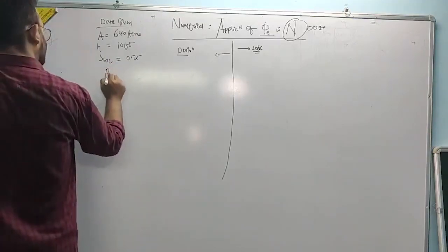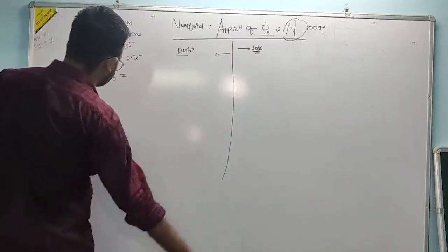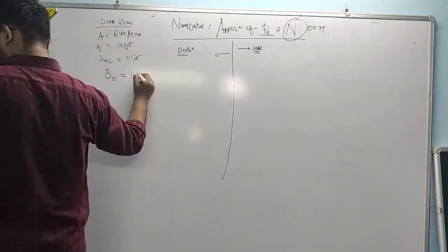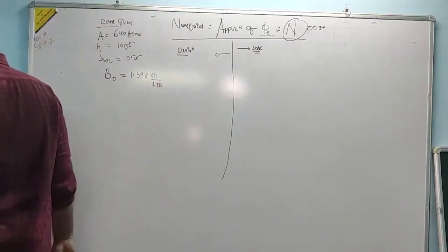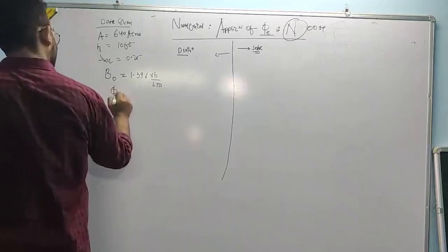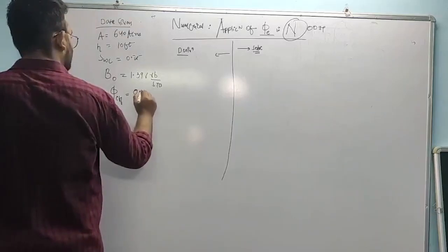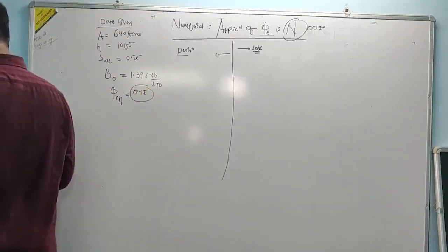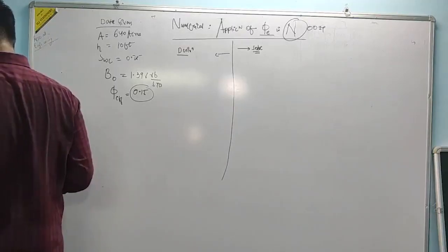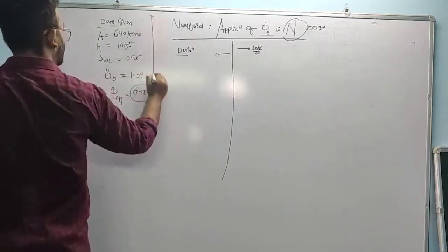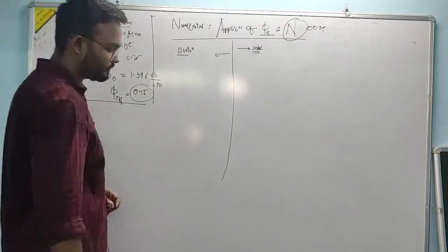The formation oil volume factor, which is just a conversion factor that takes the oil from the bottom hole or reservoir conditions to the surface units, is 1.396 reservoir barrels per stock tank barrel. The effective porosity that we have calculated by one of these methods is 0.15. You never use the percentage version of the porosity in your calculations. You always use the fraction version of your porosity, right? So what we have to find is N.